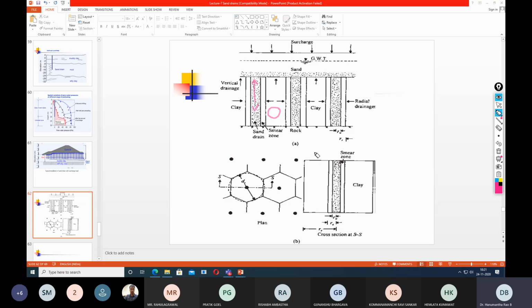That's why wherever you see any kind of clay soil, it undergoes settlement continuously, but at a very slow rate. That's because of self-weight consolidation and changes in the groundwater conditions. But when you impose the surcharge load for a particular time, I don't think so, because that effect is already nullified.